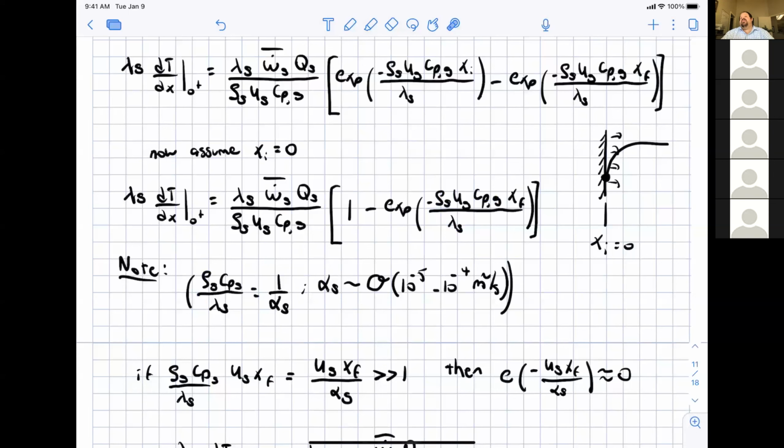especially a composite propellant, the binder is HTPB, which is basically rubber. And so basically the insulating qualities of a propellant, without any little metal wires and things embedded into it, are basically those of a rubber, which is a very good insulator. And so the thermal conductivity and the thermal diffusivity of a propellant tend to be quite low. And so